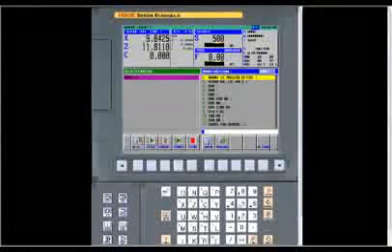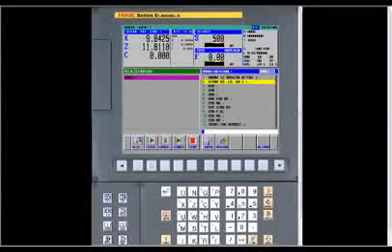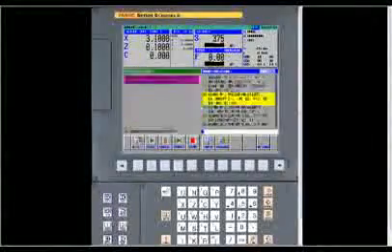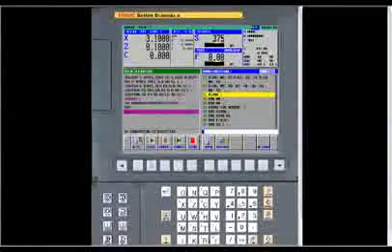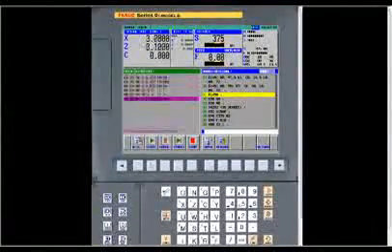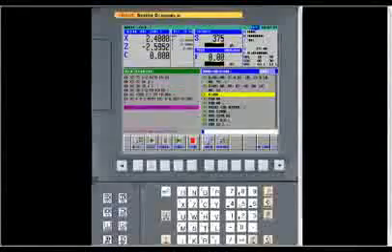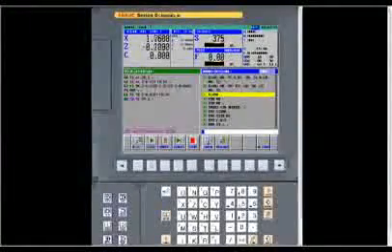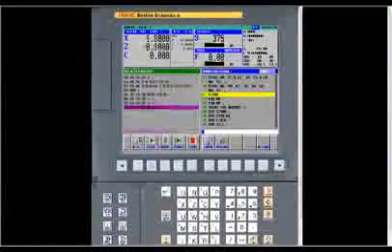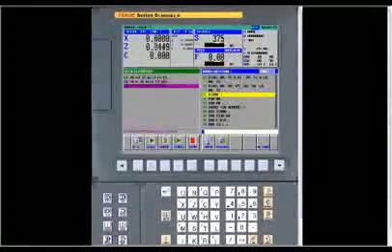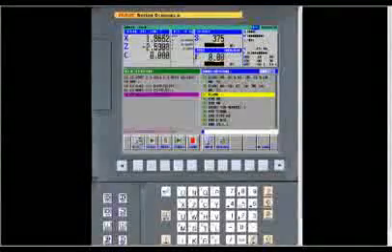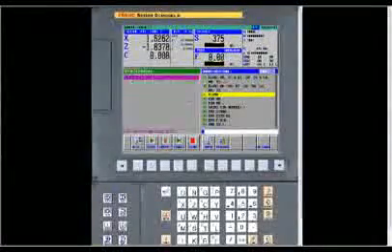Okay, so now it's got a split screen. So we press Start. See, it's going through and reading the program on the right-hand side and creating a G-code program on the left side. And they're all just straight point-to-point moves. In turning, in drilling, it'll use drill canned cycles, and in threading, it'll use a canned cycle, like a G78 or a G92.